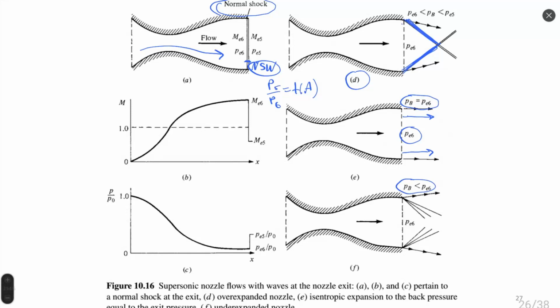We have additional expansion of the flow inside the atmosphere. In such a case, instead of having shock waves, we have a set of expansion waves which expand our flow in external space. So the flow inclines, the flow expands, occupies more space. Such three cases, case D, E, and F, we can observe on the same rocket motor, on the same launcher when it starts from the ground.